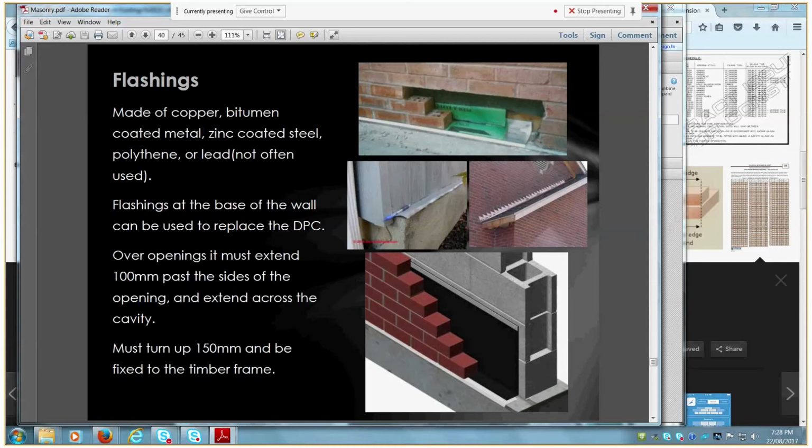Yeah. What's the cost? Yes, that's it. So flashings are typically very cheap, the materials are very cheap. But it's very important to get flashings correct and think about flashings and to be conservative when it comes to the design and the installation of flashings, because it's where many buildings fail in the moisture sense.